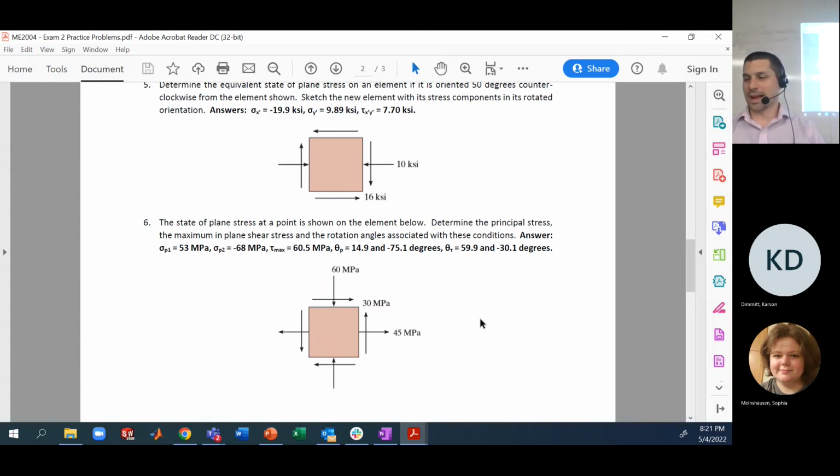And remember what we're looking at when we're looking at this two-dimensional element. It was once a 3D element that we have looked at now from the side, saying that the surface we're looking at has no stress upon it. It's a 2D element with no z direction stress, right? Just got to remember that that's how it was made. And when you're making these transformations, it's basically like cutting in a different way.